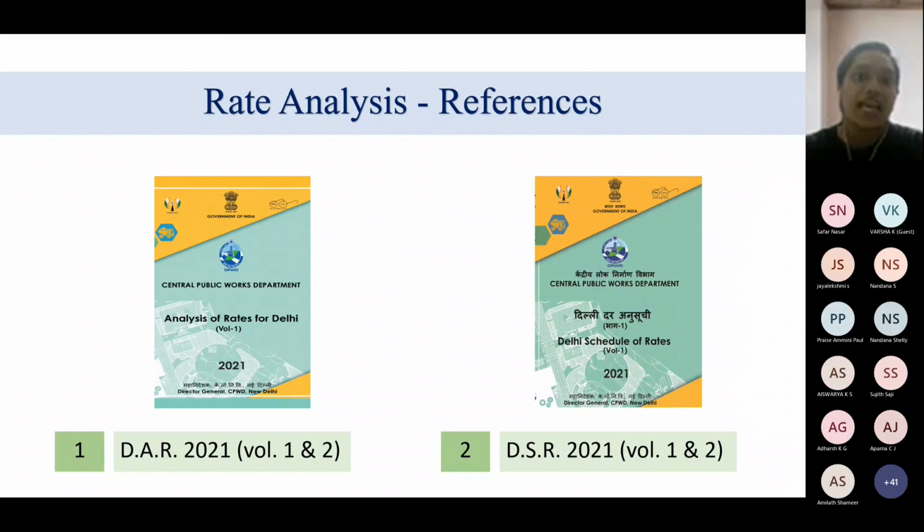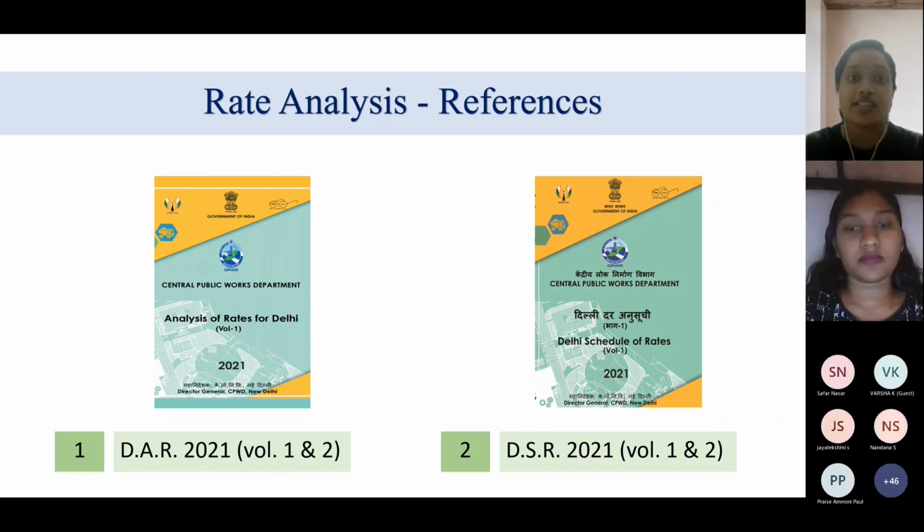In the rate analysis part, learning by heart is not that easy. But when you keep practicing rate analysis or estimations, you will learn some rates by heart while practicing. But learning everything by heart is not possible. If I give an instance, you can do the rate analysis for brick masonry and rubble masonry also. So here brick and rubble is a varying entity. The thickness of the wall will be the same, but the materials are changing, hence the rate can also vary.